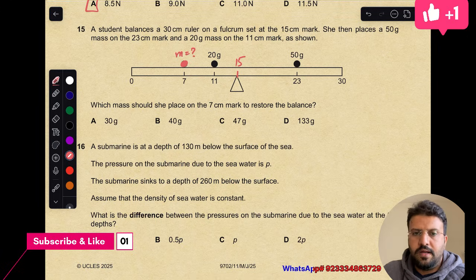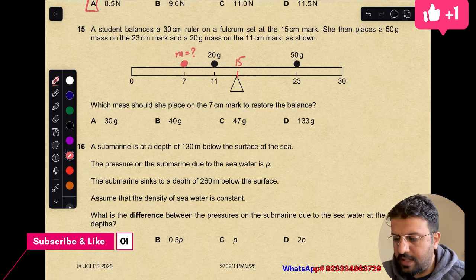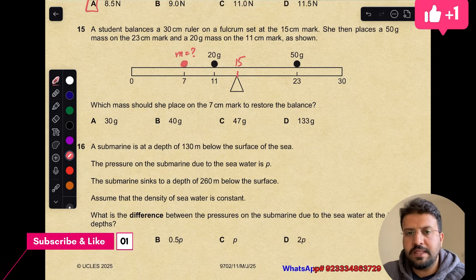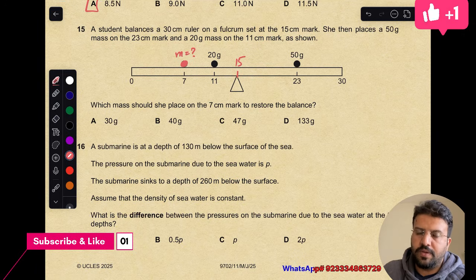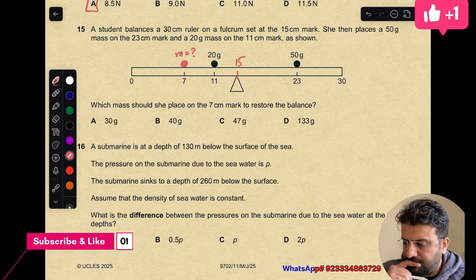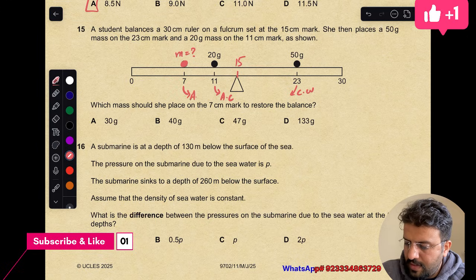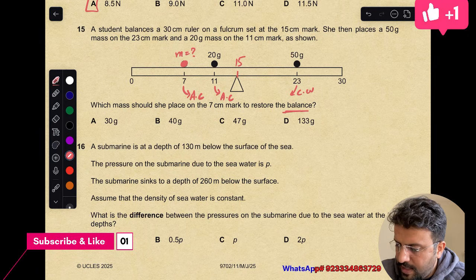When you are solving questions on moments in these types of scenarios, when things are balanced, the mass and the weights act in the same way. You don't need to convert this into weight, or even convert grams into kg. You will get the same answer in all cases, so let's take them as they are. One moment is produced there, which will be the clockwise moment. One is there that is the anti-clockwise moment, and one more is anti-clockwise. And this is balanced, right?